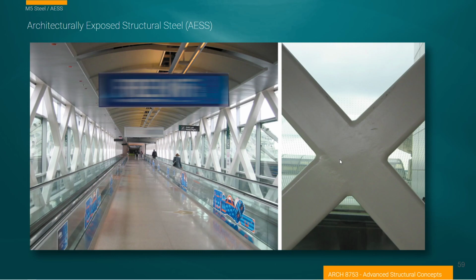And this is probably considered a very acceptable quality connection. But you've introduced this idea of a lot of welding and finishing work that has to happen where these two intersect with each other. If these had just been diagonal members, all of this work would have been eliminated, to the, I guess maybe to the loss of the appearance, but it's always a trade-off.